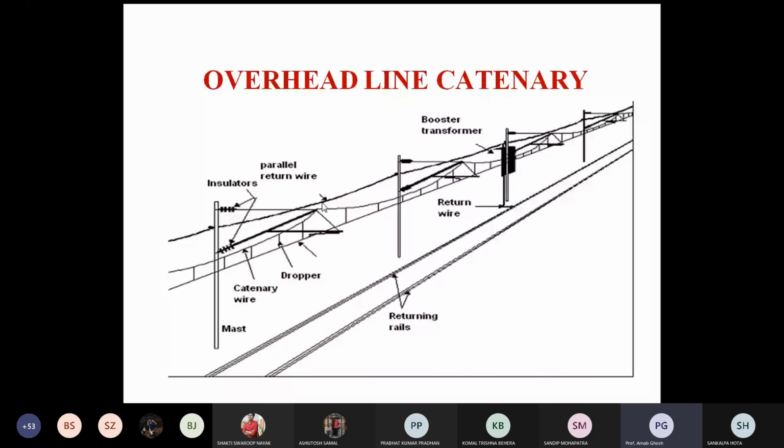The surface of the conductor is what normally carries the current. Basically, you know that due to the skin effect, AC currents normally pass through the surface side of the conductor. That's why you can make multiple conductors in ACSR form, and in between, there are steel reinforced conductors that provide some mechanical strength.